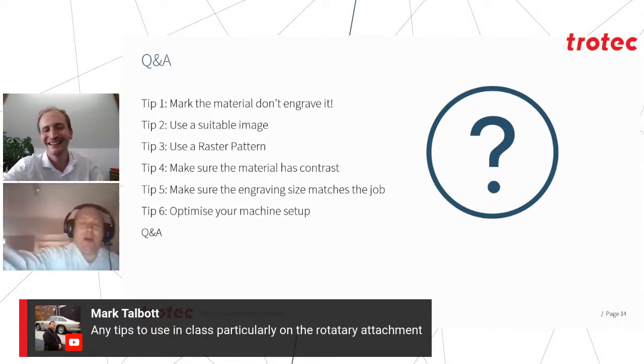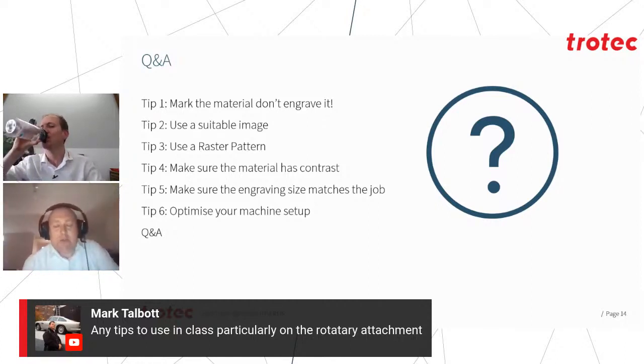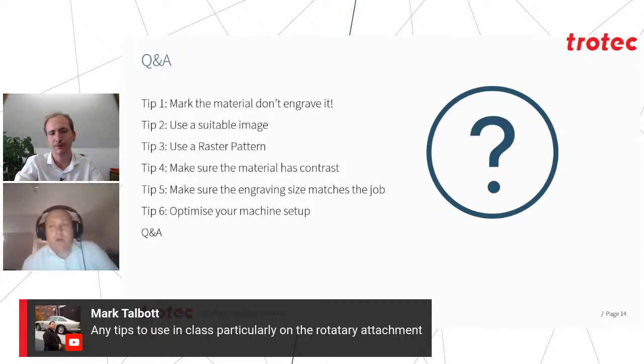Okay. Obviously, glass is one of the more difficult substrates to etch a photo into, mainly because it doesn't hold that detail particularly well. Essentially, you are shattering the surface of the glass, so your spot size tends to become a bit bigger. So if I want to put a photograph onto glass, I will generally be taking away as much detail out of that photograph as possible. And whilst Alex mentioned how you can adjust photographs in Corel and Illustrator and things like that, there's also a few handy apps that you can use. I use one called Pencil Sketch quite often.